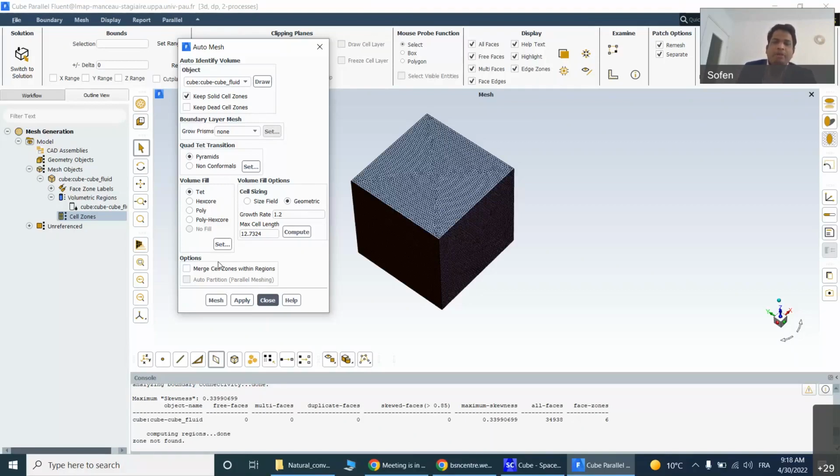Now, to capture the viscous sublayer, if you are solving a flow over solid surfaces, you need a very fine and uniform mesh near the solid surfaces. Normally there are two ways to deal with the flow across the solid boundary. One is the low Reynolds number method. One is the wall correction. What is the low Reynolds number method?